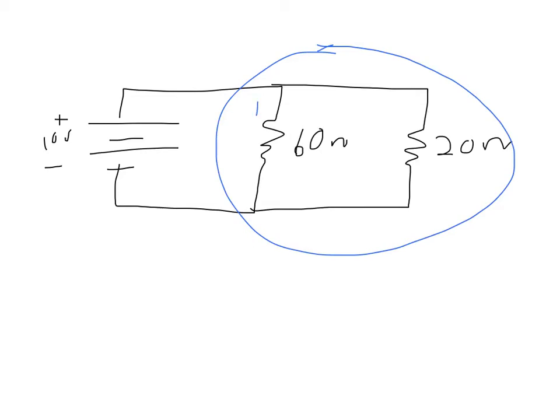There's 10 volts across this one. There's also 10 volts across this one. If I took a meter, I would be able to measure that. So I could also find the current through each of them using Ohm's law.